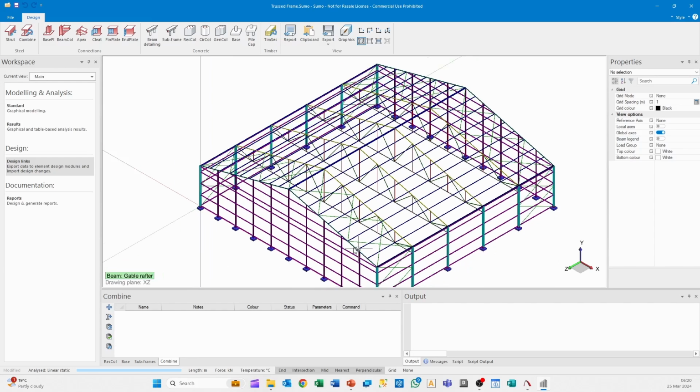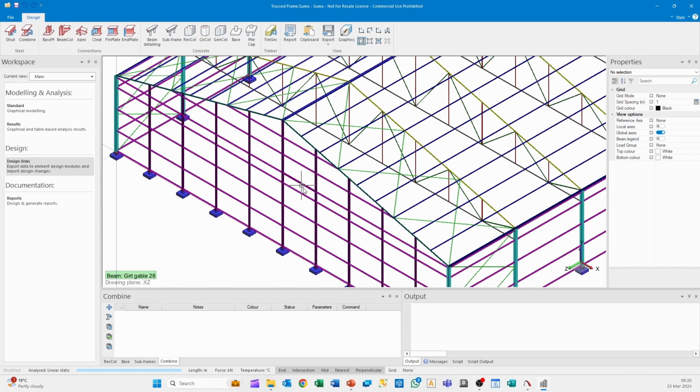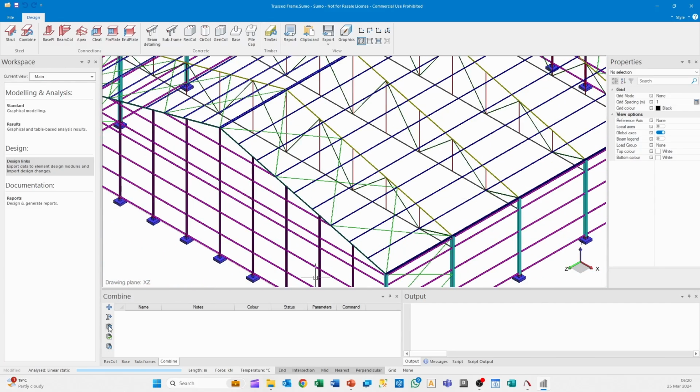So the program will automatically generate design groups for you and assign those particular members to that design group, which is amazing. So just so that you know that the design group is quite limited in its scope of members that it can deal with. And at the moment, it is limited basically to your H sections, I sections, and a few of your hollow sections, and I think channels, but I do speak under correction. You've got optimize all, you've got evaluate all, and you've got export all.